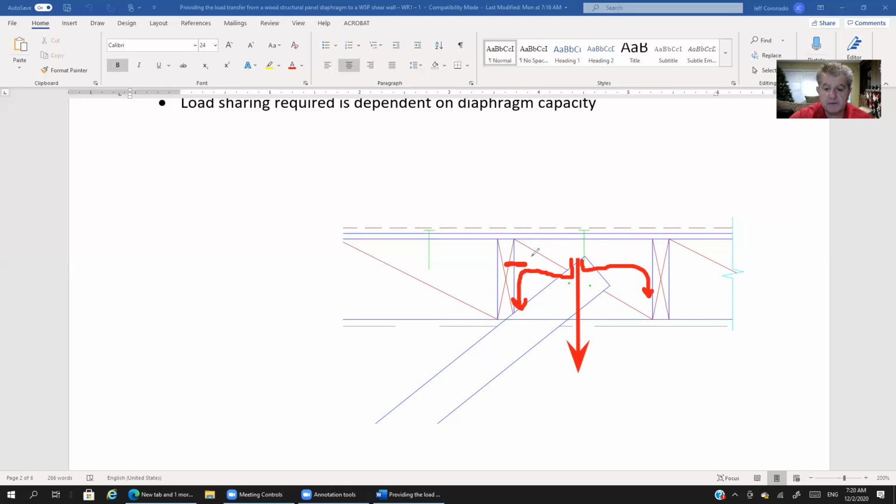That's not the purpose of this tutorial. I'm sure that's covered in another session in Bridging the Gap. But we do need to provide a load transfer there. But the idea is that then the load does migrate from the block into the rafters. And the rafters do resist vertical load. So we would cover that vertical component by transferring the load into the rafters.